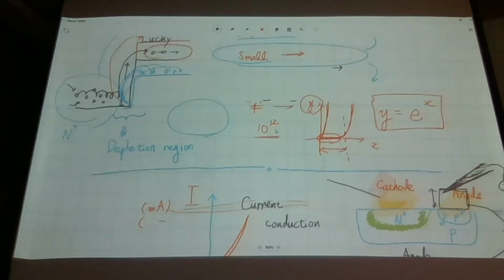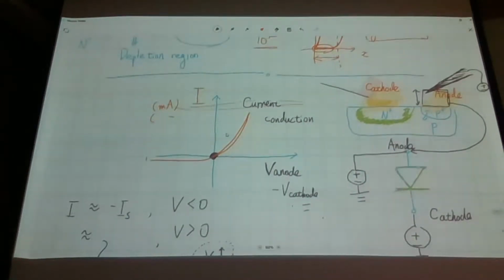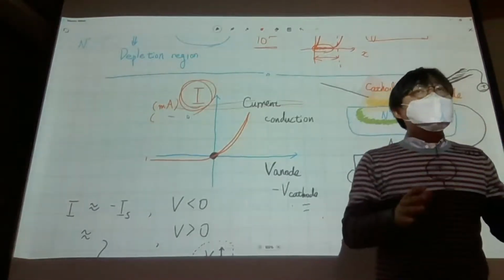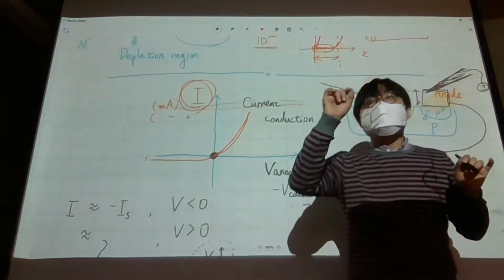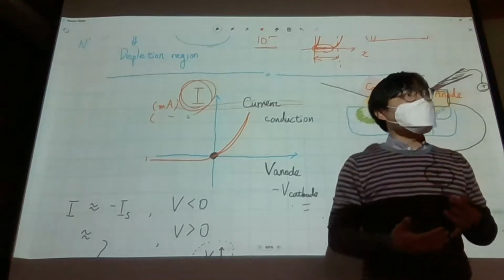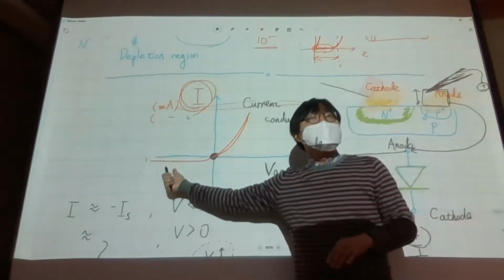So what I want to say is, always think about the range of your graph. This is one thing that is very easy to overlook. Usually when we draw IV characteristics, sometimes I can say that the current is negligible, or there is almost no current at all. I can say that in plain English. However, please note that if we have a look at the graphs in a really magnified view, for example, if we are talking about femtoampere scale graphs, then that becomes a really meaningful quantity.